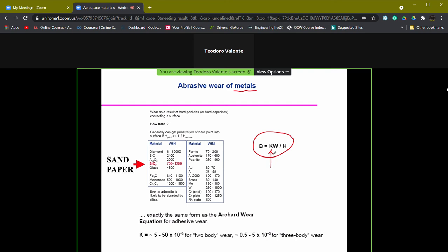There is a universally accepted condition which must be kept in mind to understand if abrasive wear can happen or not, and it is quite simple. We can have abrasive wear if the hardness of the harder material is at least 20% higher than the hardness of the material which will be consumed.